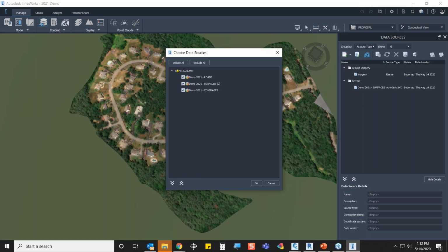So yes, you may have to see yourself creating cleaner drawings to only export the geometry that you want, that we choose what to kick out, because sometimes it may hang up on trying to read everything that's in that drawing. You may have to use data shortcuts and promote things to be able to have a smaller file. In my case here, all that you see was the terrain, the corridor, and the surfaces that were generated there.